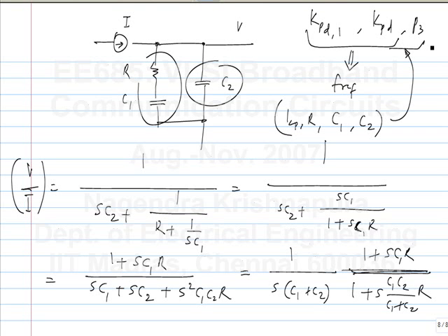Now obviously the actual transfer function, this is V by I. So you can reduce ICP and increase the value of R, reduce the values of C, and everything will remain the same. That is simply scaling the circuit. If ICP was 10 microamps and you had 1 kilo ohm and 100 picofarads, you can make it 5 microamps, 2 kilo ohms and 50 picofarads. The transfer function will be exactly the same. Now how do you choose between the alternatives? The 50 picofarad one will have a small area, right? Smaller components have smaller area. That is one constraint. But it may get harder to realize a smaller current source. You will get mismatch, and maybe more noise. So there will be a trade-off there also.